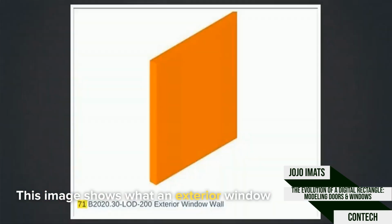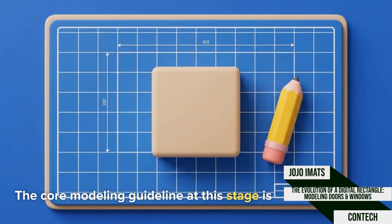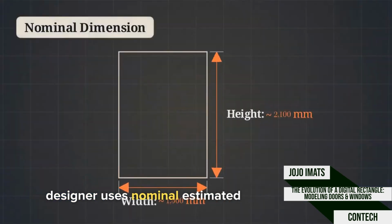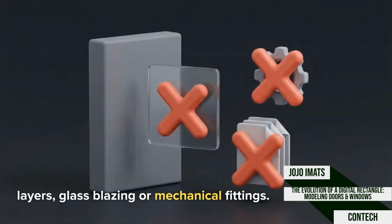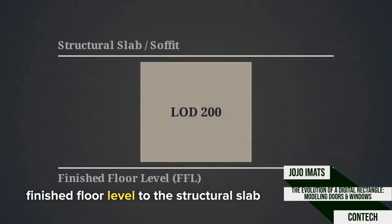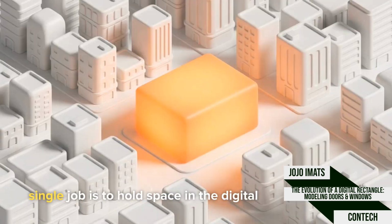This image shows what an exterior window wall actually looks like at level of development 200. The core modeling guideline at this stage is simple. If actual dimensions are unknown, the designer uses nominal estimated dimensions. This simple block does not need internal layers, glass glazing, or mechanical fittings. It merely needs to span vertically from the finished floor level to the structural slab above. During this early phase, the component's single job is to hold space in the digital world.